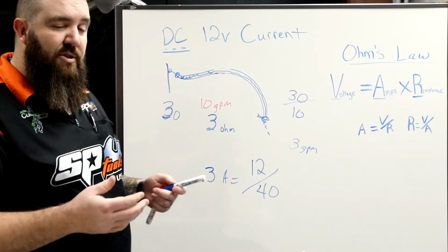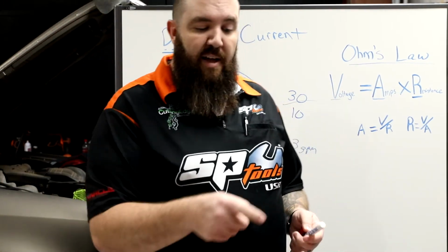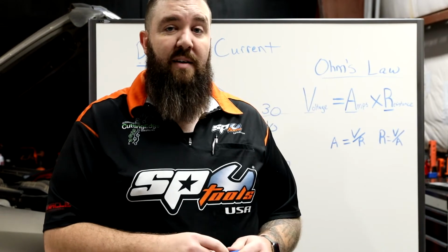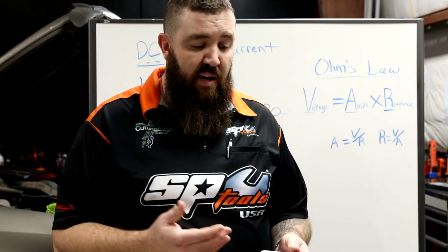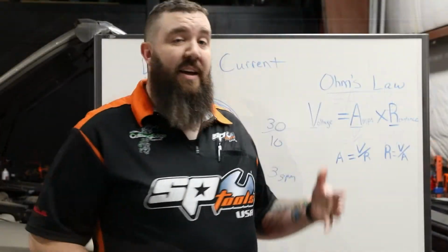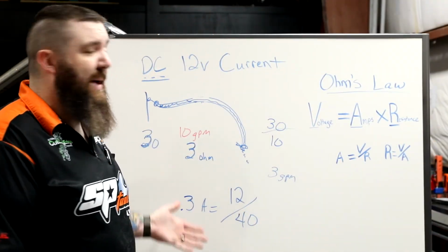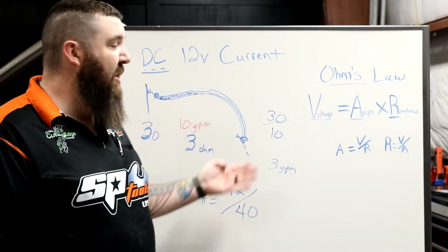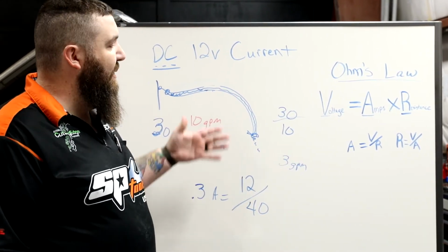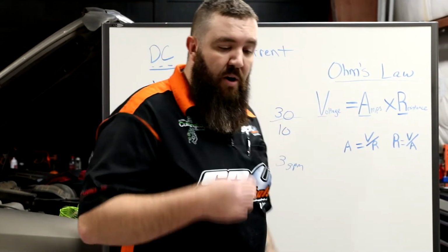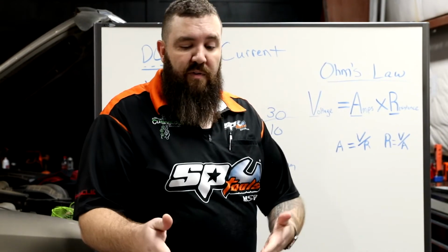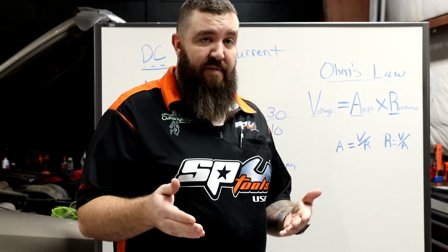So the less amperage you have going through your system, that is how you can tell that the light bulb has dimmed quite a bunch, because we have less flow of electricity going through the system after that 40 ohm resistor. That's how you're going to use the actual math and equation to figure out what the missing leg within this system is. Now if for some reason we don't know how much resistance is right there, then we need to use our meter in a different fashion.